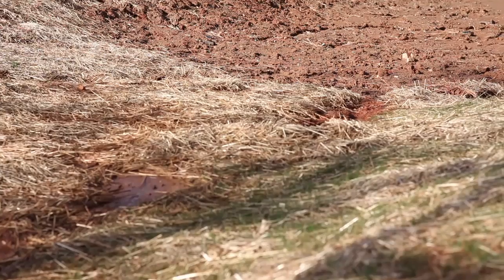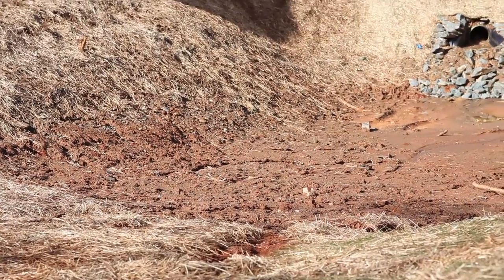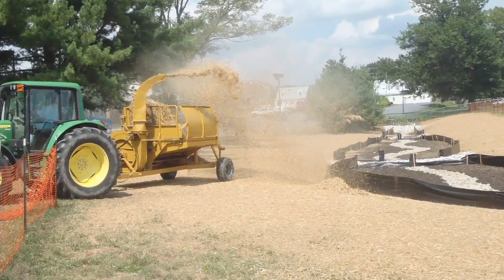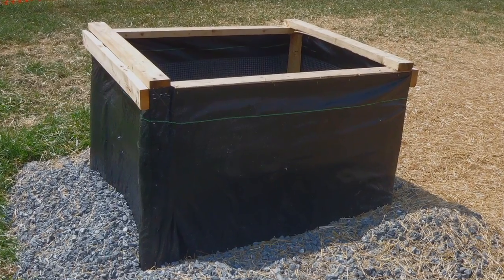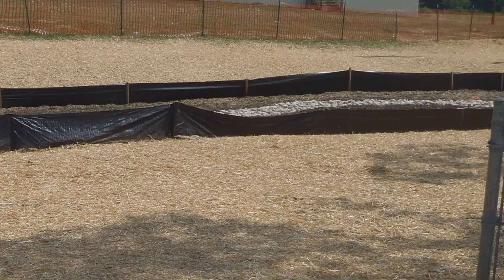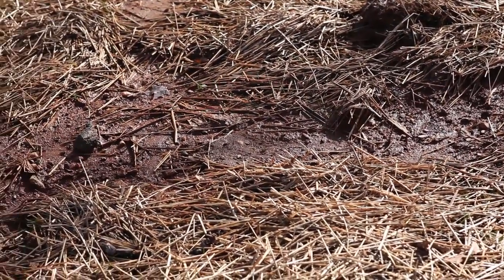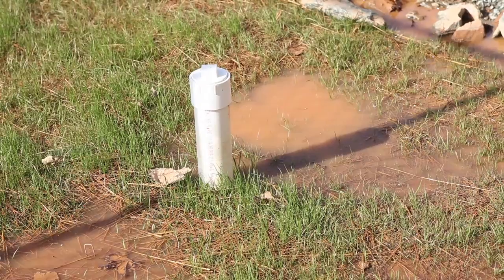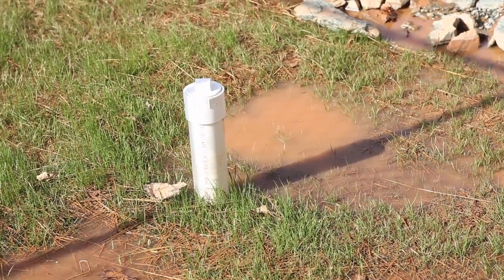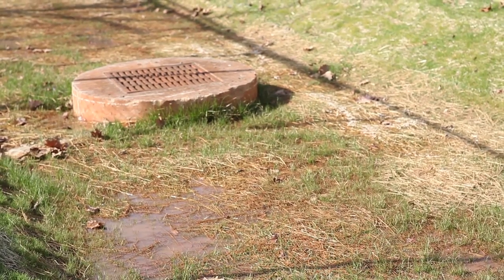Immediate problems can occur if the contributing drainage area is improperly stabilized. This, along with sediment and erosion control, are essential BMPs for all construction projects. Runoff from rain events during or immediately following construction can send a flood of sediment-laden water into the practice, which leads to the clogging of the filter media and results in a BMP that does not drain or function properly.